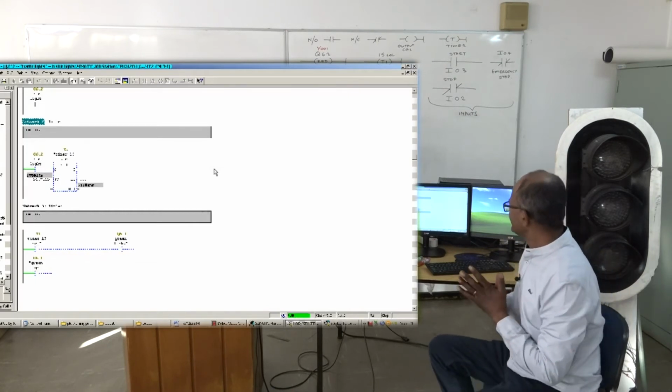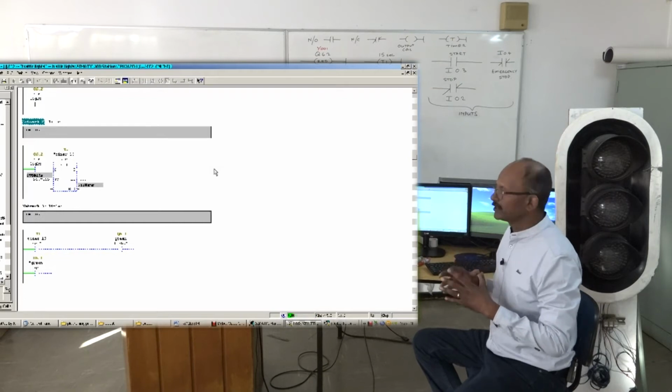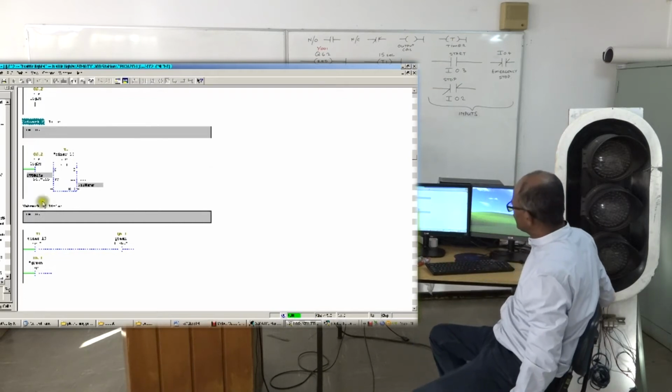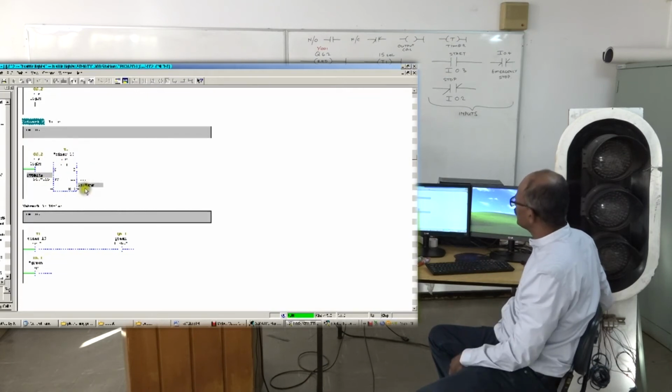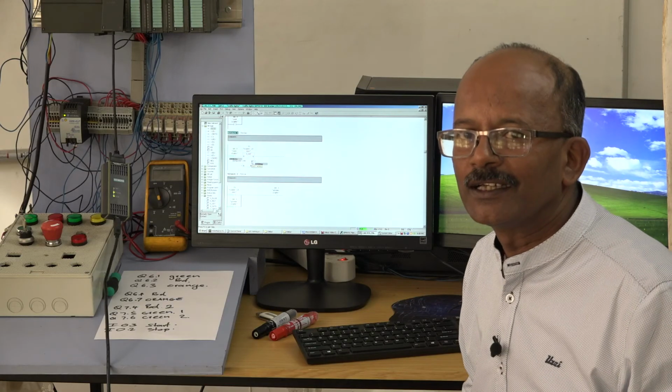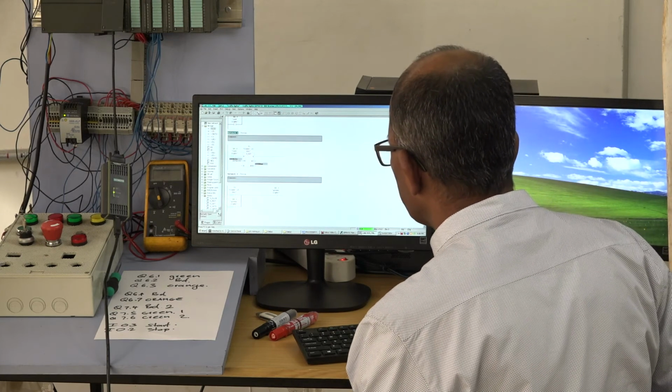Now, this is where you actually need to latch the timer to keep it on, because you will find after it actually timed, it's an on-delay timer, it actually lost its power. It's no more energized, right? So instead of using a normal timer, what we actually do is use what we call a retentive timer. Okay, so it's an on-delay retentive timer.